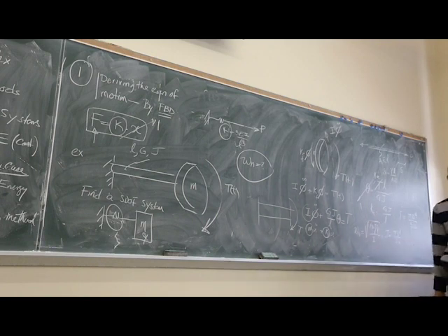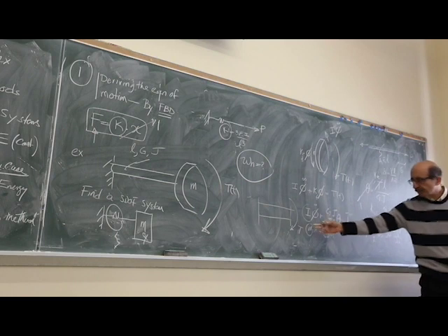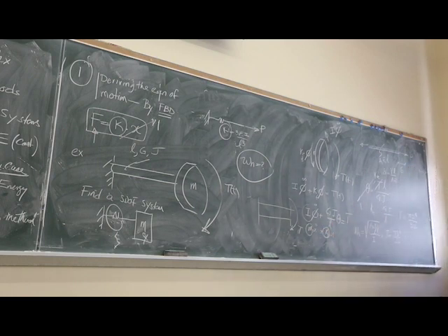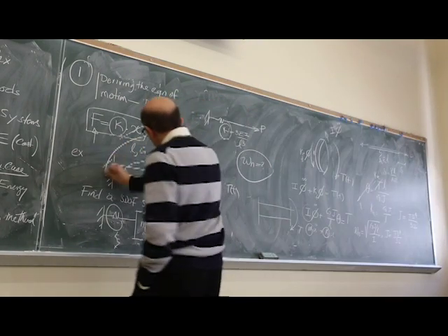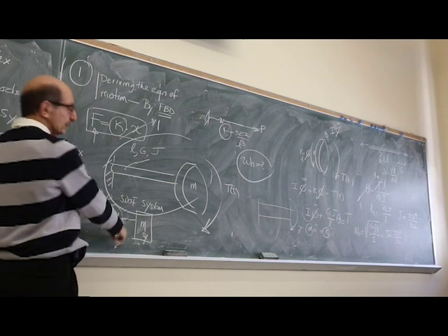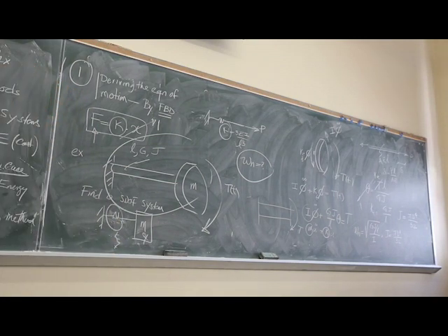But it's a simple example that shows you if you can derive the equation of motion, and based on the simple definition of the stiffness, you can find the mass and the stiffness of the system. Or in other words, you've replaced this with this little innocent looking single degree of freedom system.